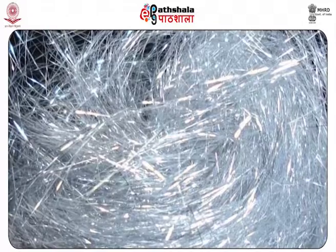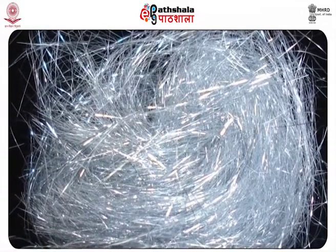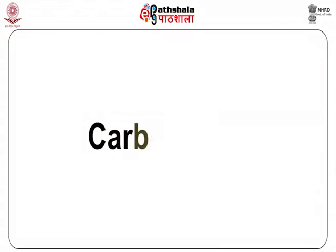Metallic fibers. Metallic fibers are manufactured fibers composed of metal, plastic coated metal or metal coated plastic or a core completely covered by metal. Gold and silver have been used since ancient times as yarn for fabric decoration. More recently, aluminum yarns, aluminized plastic yarns and aluminized nylon yarns have replaced the gold and silver. Metallic filaments can be coated with transparent films to minimize tarnishing. Metal fiber may also be shaved from wire, that is steel wool, bundle drawn from larger diameter wire, cast from molten metal or grown around a seed, often carbon. Carbon fiber.